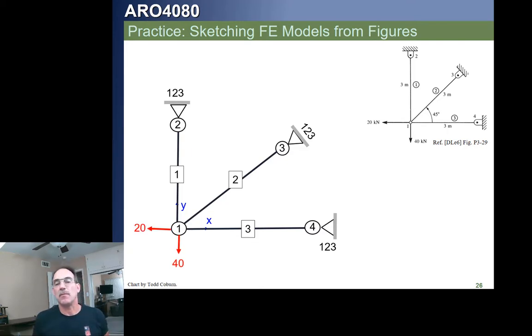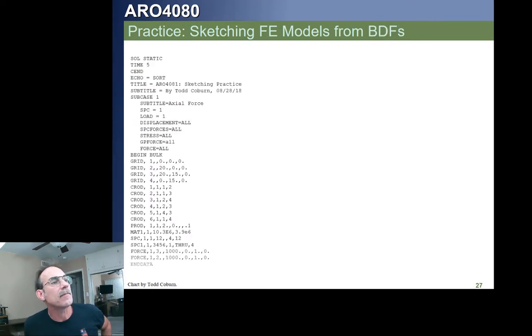Now, if you're running a NASTRAN model for many of the solvers, if you don't put in a constraint in this is the constraint in all 3 directions, but actually this loading, what NASTRAN sees is no stiffness coming out of plane, so this can flap about like this. So sometimes we'll also put like a 4, 5, 6 at those 3 nodes just to keep NASTRAN from going singular. And because the way this is loaded, that should not affect your results at all because these rods don't have any means of transferring those degrees of freedom up to those elements.